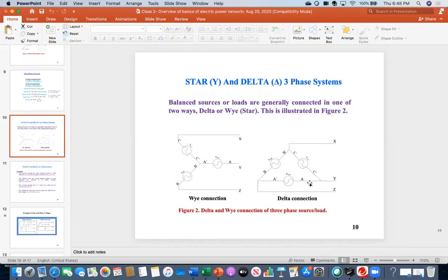Now come back, everybody, to this side. For example, you have an ammeter. You connect the same thing. In this case, these coils are called the phase current or phase voltage, but X and Y, these portions, are called the line. Now you connect a voltmeter here between X and Y, and for example you get 100 volt. Now you connect another voltmeter here between C and C prime. What should be the reading now? Same, because this point is essentially the same point. So in this case, the voltage is the same.